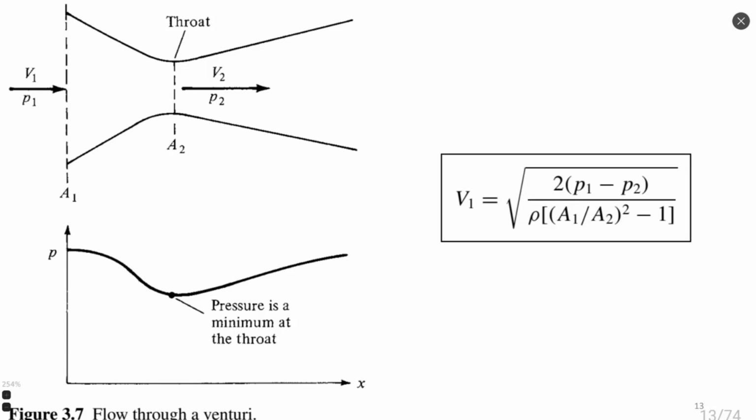We may also see that pressure is changing according to the Bernoulli equation, right? Pressure is higher at the entrance, where velocity is smaller, then pressure drops in the throat, where velocity is bigger, and then rises again at the exit of our Pitot tube or Venturi.